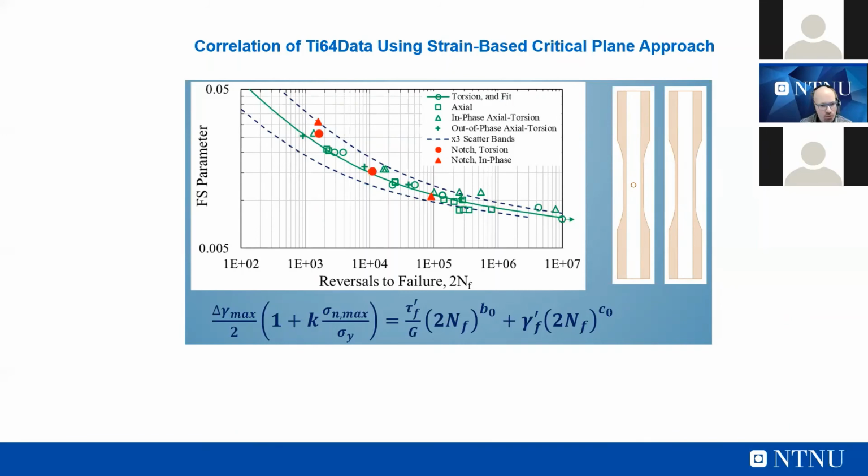Of course, dealing with this multi-axial approach, you can also consider that the strain energy density can be applied under multi-axial conditions. But to be honest, the physics is better explained by the Fatemi-Socie parameter, because the physics behind fatigue is completely summarized in this criterion. The strain energy density approach is more of an engineering approach that can also be used for multi-axial loading,